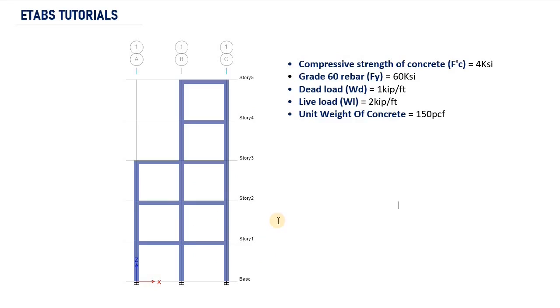Now, this was actually a research project of mine. Due to its irregularity in height, I performed a nonlinear pushover analysis on the frame to determine the location of plastic hinges on the frame.